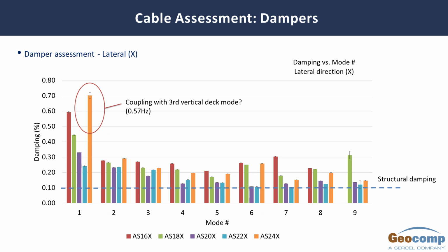The other thing you need to be very careful about is that when we look at the damping performance, we should extract the damping ratio information out of the cable. If we are only looking at the vibration signal, for example in a cable plucking test, where you hit the cable or pull the cable, it's very easy to misread the results. So you have to be very careful and do the right damping ratio estimation to understand the real damping behavior.